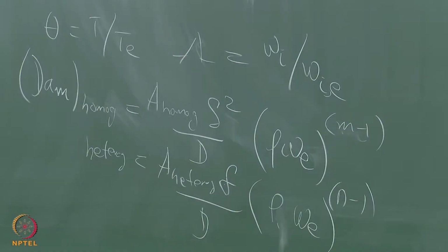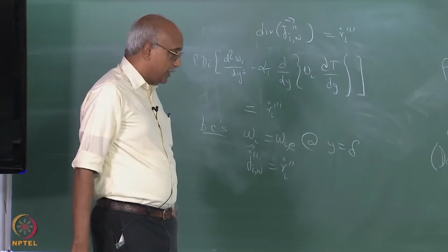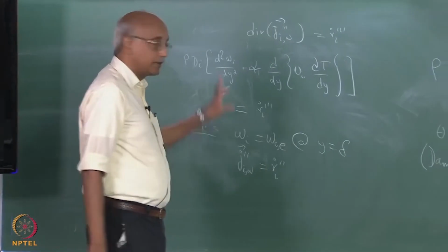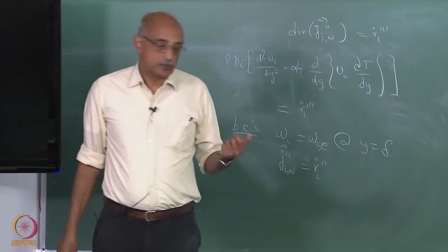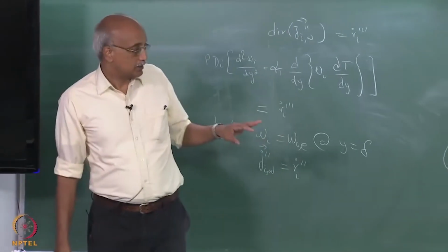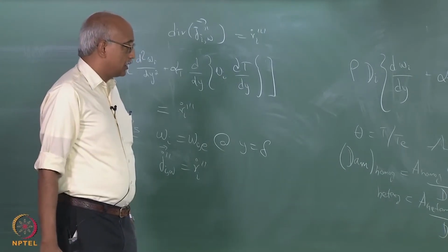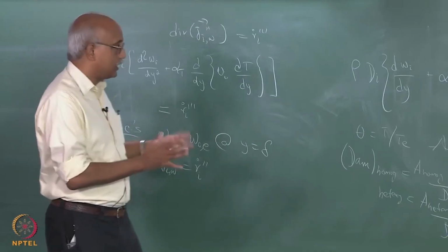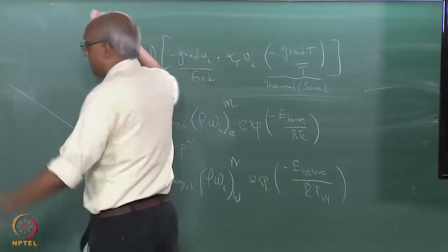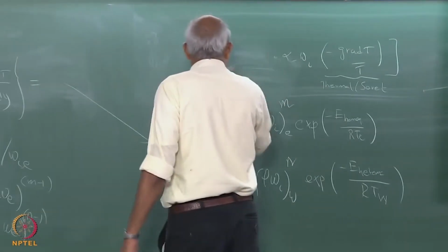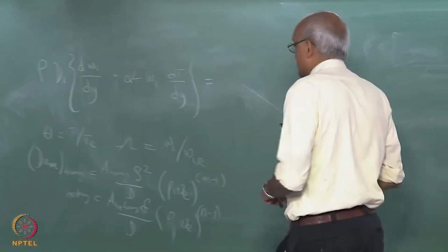So, these are the corresponding Damköhler numbers, and as you can expect, the Damköhler numbers are related to those temperatures that we talked about, T12 and T23. By evaluating the Damköhler numbers, you can estimate those temperatures as well. Okay, so now that you have defined certain dimensionless coefficients, you can actually rewrite those equations also in non-dimensional terms, in terms of theta and omega.